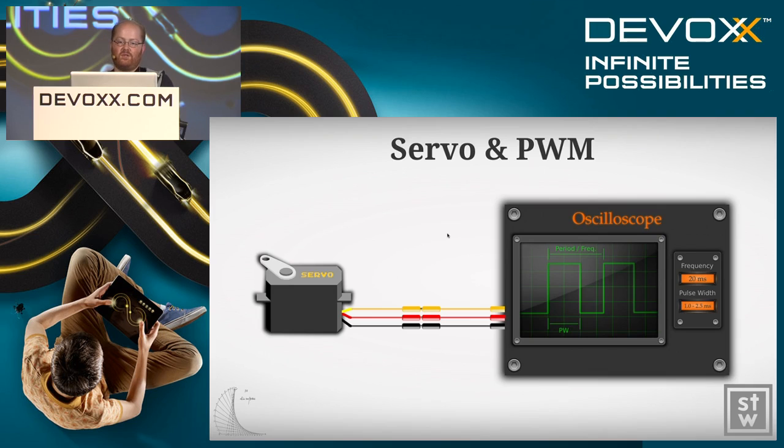The servo uses pulse width modulation, and you can create that on the Raspberry Pi. I tried software pulse width modulation because the original Raspberry Pi only has one pulse width modulation GPIO pin. But then I experienced that it's not precise enough and also uses a lot of CPU.